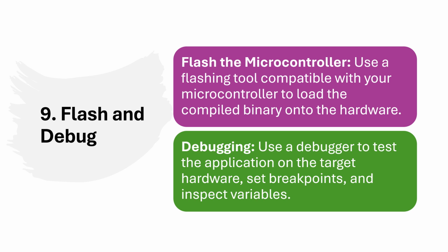like CANalyzer or CANape. For example, in CANalyzer, you can monitor and analyze CAN bus communication, debug the ECU, see real-time ECU data, and then simulate different issues with the network nodes. With CANape, you can change parameters on certain things. Once you connect with the hardware, you can change some parameters and see how the system reacts, and do the data logging and those sorts of things.